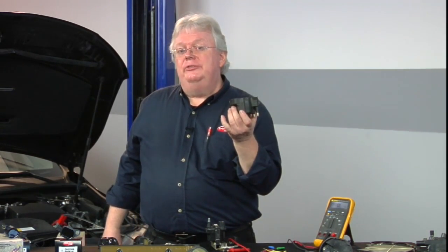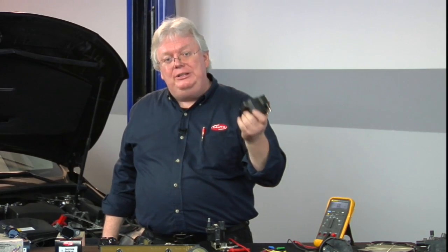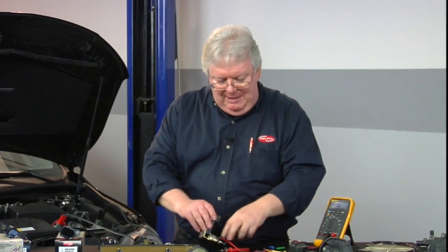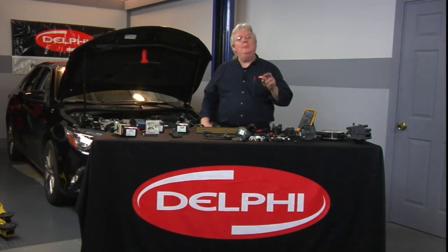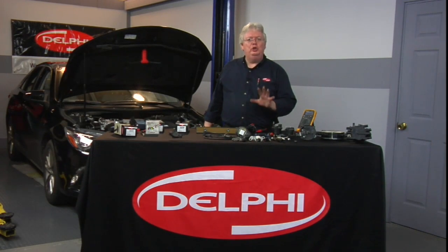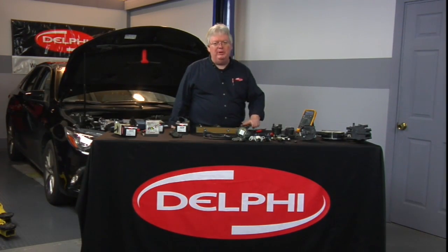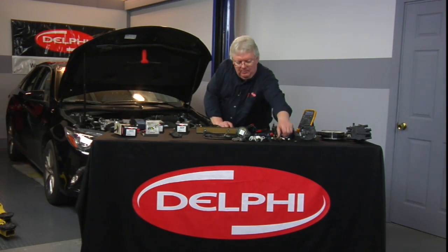So this coil, at least on the surface, electrically, primary and secondary have good continuity. It's good. So we have a couple old-fashioned coils that we've tested, and you're probably familiar with that and have been for years. Now let's apply that knowledge going forward to a Coil-On-Plug Ford style 2-wire. So we still got the output of the secondary. I guess you could call that the third connection where the spark plug is going to go.